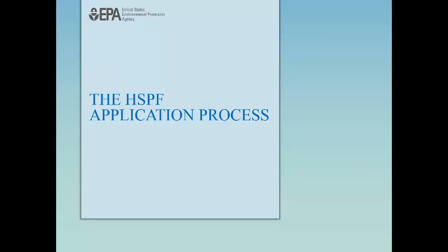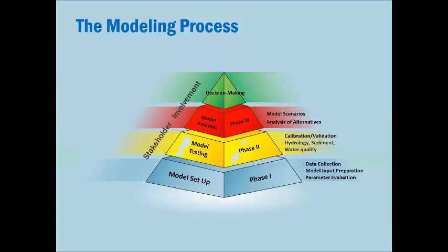I want to go over briefly the HSPF application process, the steps involved in actually applying HSPF. We've shown it here as a pyramid, with the bottom phase being the model setup, phase 1, involving data collection, model input preparation, and parameter evaluation. The second phase is calibration and validation of all the constituents: hydrology, sediment, and water quality.